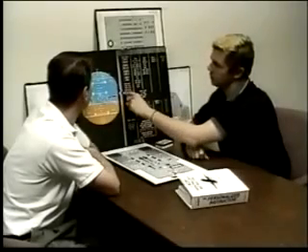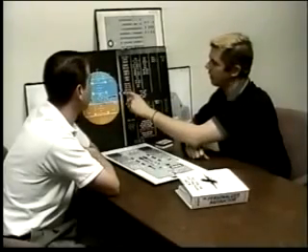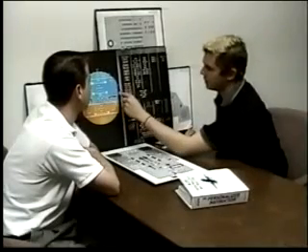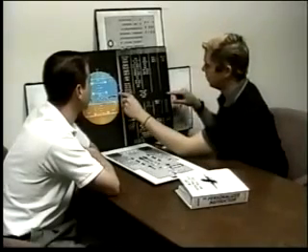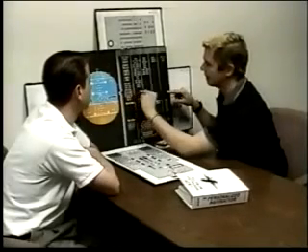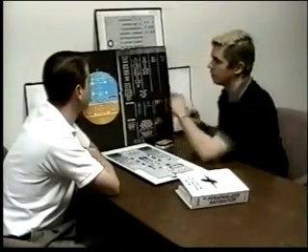In a Boeing, it's basically a flight idle descent for every step. In Airbus, it's not. In Airbus, we do a flight idle descent to our first constraint, but after that it does what's called a geometric descent, which says if I need to be at this altitude at this point, and I only need to be 1,000 feet lower, 50 miles away, it'll calculate a constant descent down to that path, which is very different from the way you used to operate in the Boeing, which means open descent and descent mode are very different from each other.